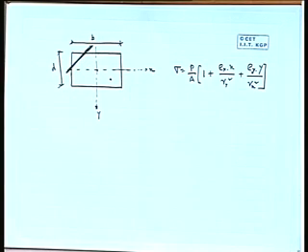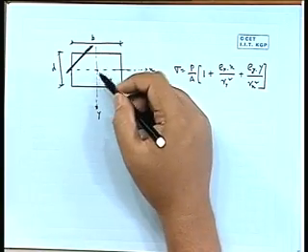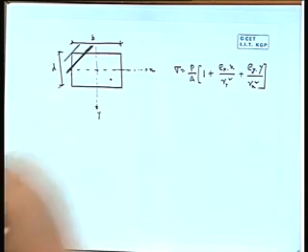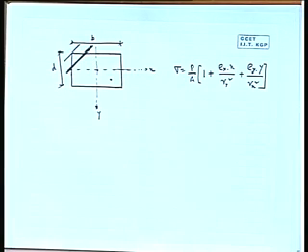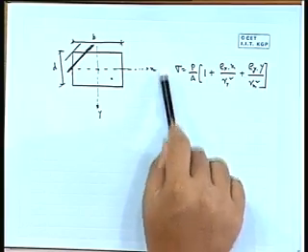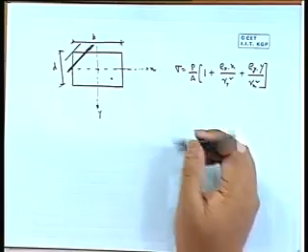Now if we don't allow the tension within that section, the line should pass along this. That will be the extreme, right. So if we are interested that everywhere it should be compression, so there will be no tension. So this line will not allow it to enter inside. So if you give a high value of Ex and Ey, definitely tensile stress will be generated, and there should be some line beyond that. Or we can say this sigma, this line is basically the 0 line. So if that is 0,